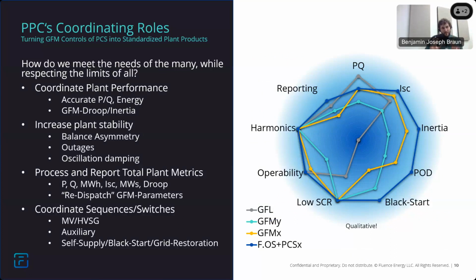So that's been the focus on the inverter, but now coming back up to that holistic view again, what is the role of a plant controller? So a power plant controller, PPC, what is its job? If the inverter is in grid forming and it's doing all of these great things, it's holding frequency and voltage, why do I even need a PPC? Well, in many ways, the role of the PPC becomes even more important.